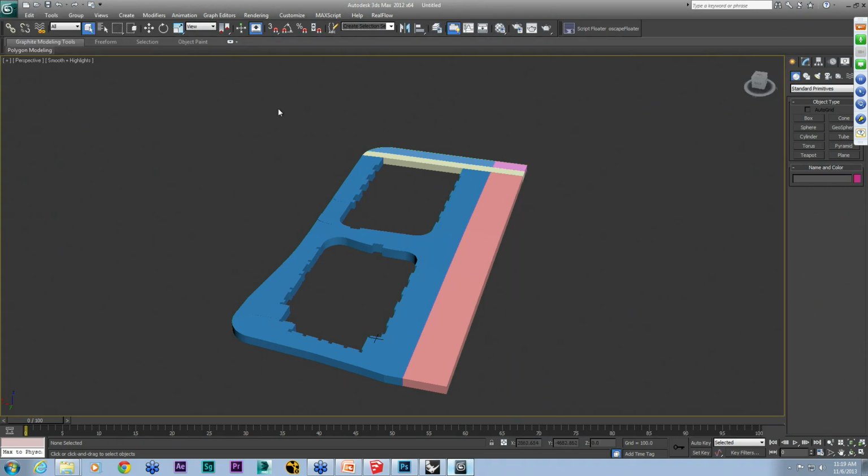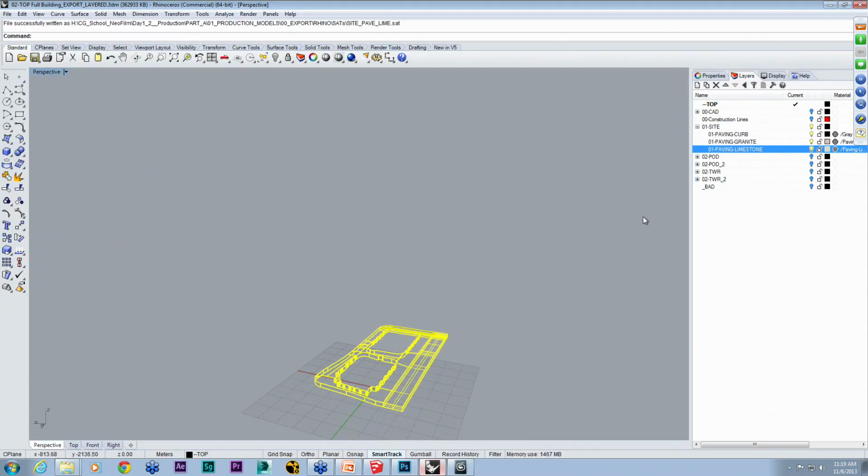And as you're working through that Rhino file, like I was saying about particular things, some layers have mesh bodies and some layers have curved items. So you can actually select and export out different things in different ways. And this way you can make sure that you're actually getting the entire model from Revit into Max and that those meshes are working properly.